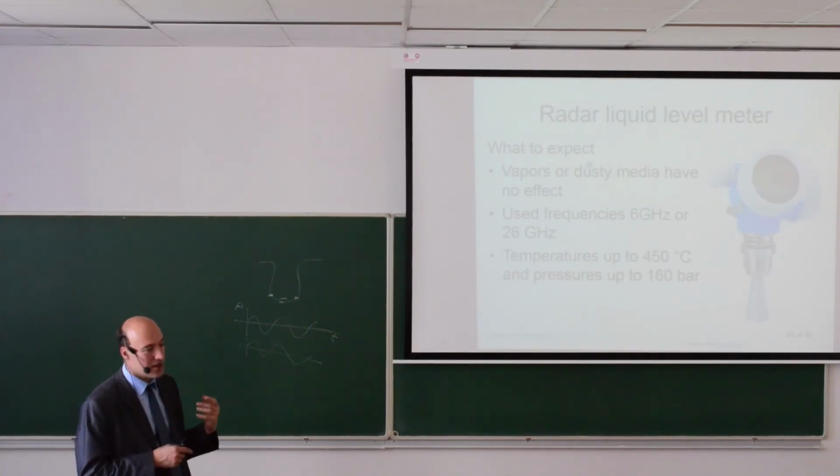If you are increasing the bandwidth, then the accuracy gets better. So some industrial liquid level sensors operate at around 80 gigahertz frequencies, and you have roughly 3 times higher range accuracy. The accuracy can be under 1 millimeter, so it's quite accurate, but it's also quite expensive.